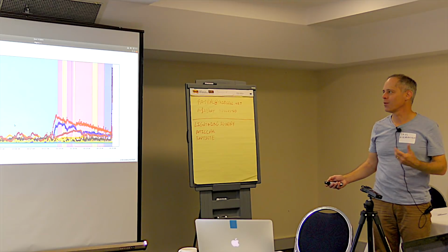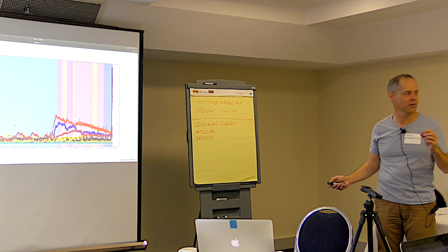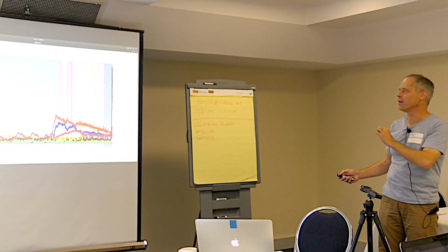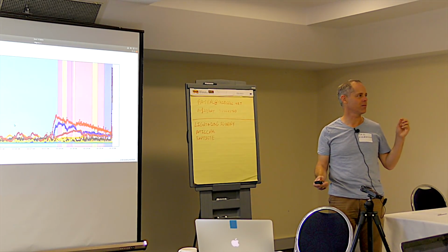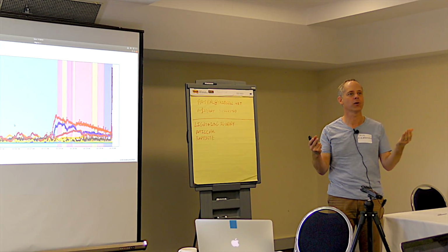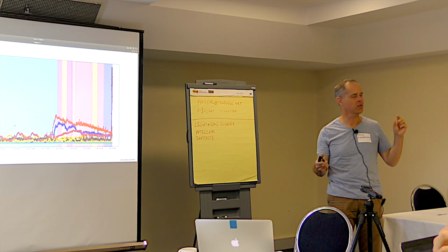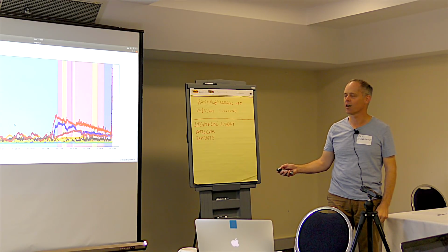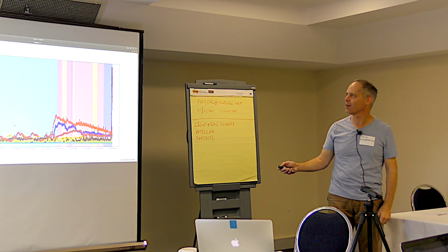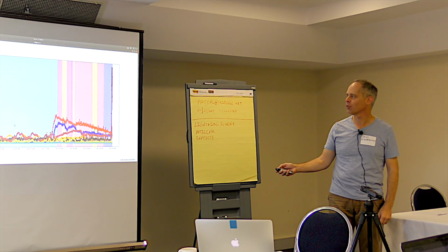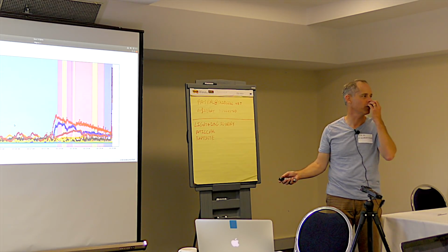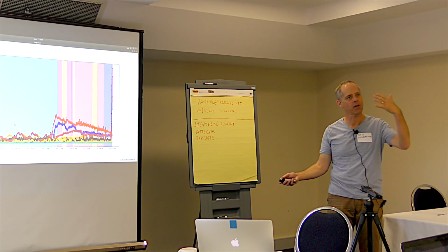All right. So, this was an interesting log, and the reason I've got this log in here is because it illustrates how the current method of doing failover between EKFs is not foolproof. Because an EKF is classified as failed if the normalised innovation goes over 1. Now you'll notice here that the velocity innovation and the barometer innovation levels, normalised levels, don't get to 1. So it continued to use those sensors, but the output, the vertical velocity and the vertical position is incorrect, and that caused the vehicle to gain height.